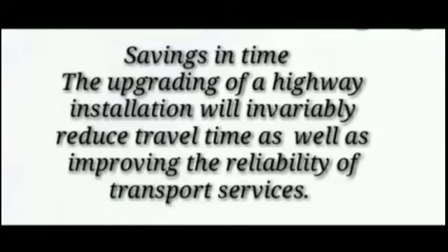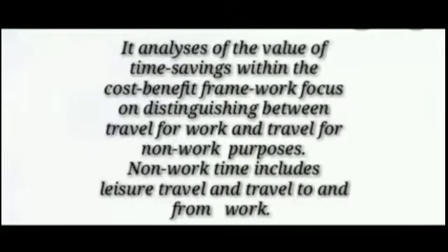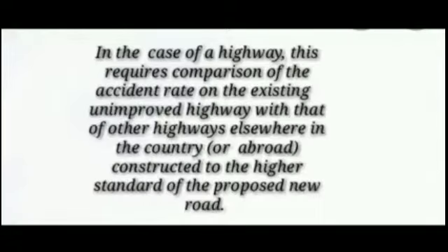The upgrading of a highway installation will invariably reduce travel time as well as improve the reliability of transport services. It analyzes the value of time savings within the cost-benefit framework, focusing on distinguishing between travel for work and travel for non-work purposes. Reduction in the frequency of accidents. In the case of a highway, this requires comparison of the accident rate on the existing unimproved highway with that of other highways elsewhere in the country constructed to the higher standard of the proposed new road. Normally, the higher the standard of construction of a highway, the lower its accident rate.